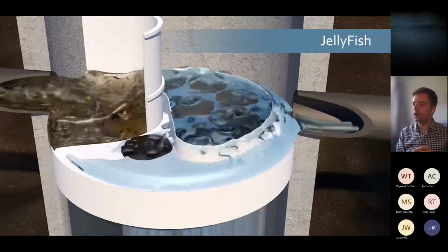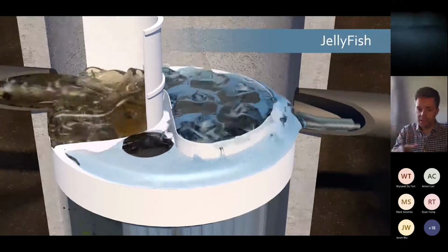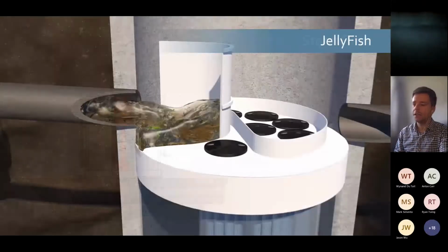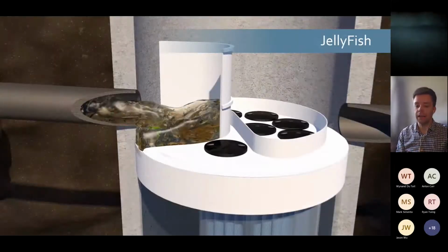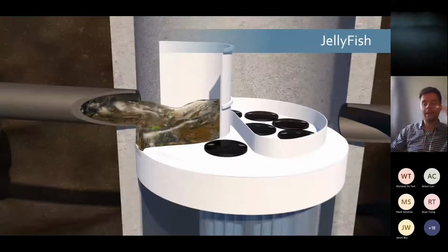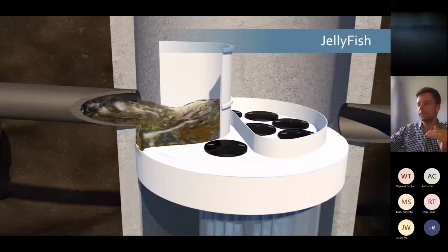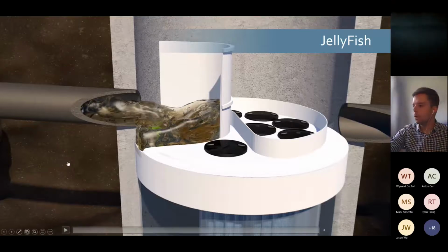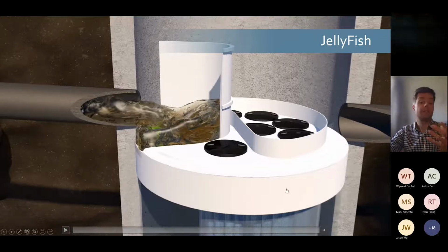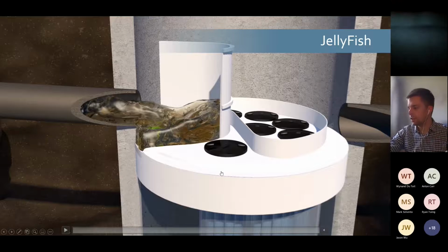As the water flows out, you can see there's that central backwash pool, and what that means is as the device then drains down, you kind of have a negative head, and that forces water to drain down from the back through these filter cartridges, and that provides an element of self-cleaning. And this drain down cartridge here allows us to equalize the pressure.